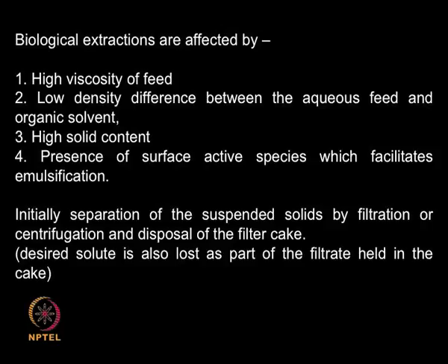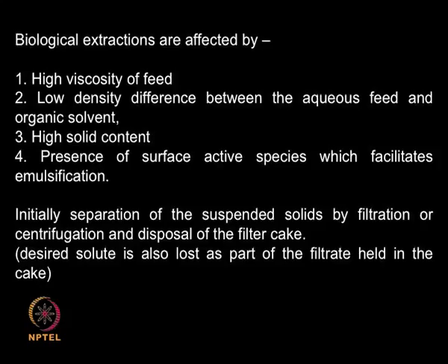Now if you look at biological systems, they create many problems during extraction unlike a normal chemical system, because the feed will have a very high viscosity because of presence of cells, biomass, intracellular material, DNA, cell debris and so on. So the viscosity is going to be very high. So obviously your extraction efficiency is low.